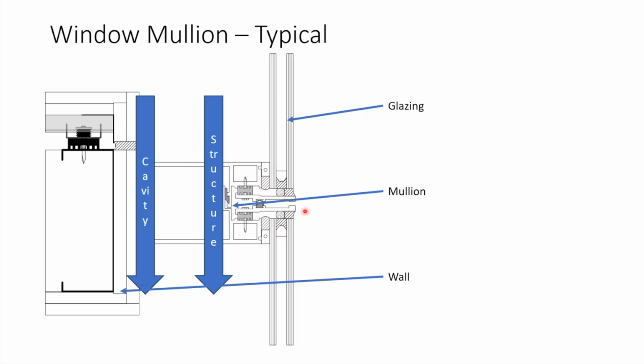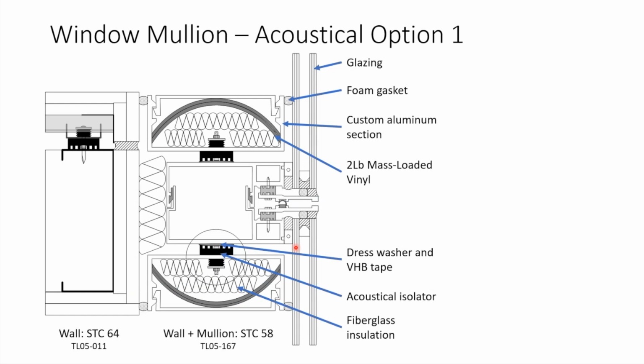Even if there is a bit of a break in here, you can get some sound transmission this way too. So one way to do that is to add isolated mass. Same thing we're doing when we're adding drywall on resilient channel or isolation clips or something like that, right? But that mass needs to look good.